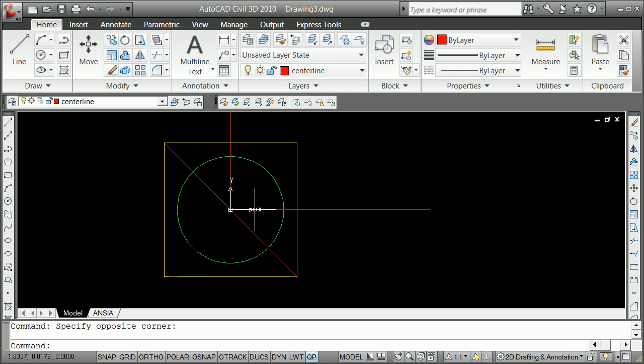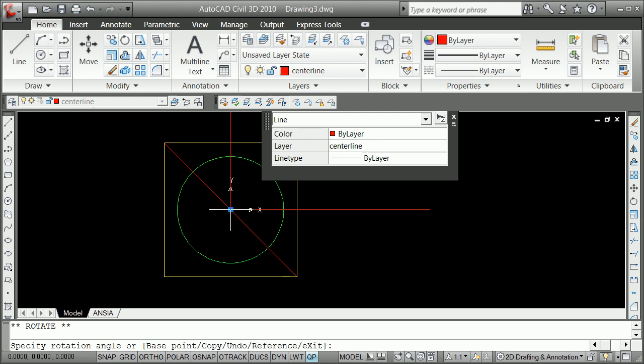Finally, we remembered in class, we're almost getting there. We wanted to make a tooth of a certain degrees. In class, you had to know that you want to pre-calculate very often, or get used to knowing that if you're going to divide a circle up, you need to know that a circle is 360 degrees or 2 pi radians. So I was going to divide mine into 60 teeth. So the way I can do is I can grab that, I can left click, spacebar, get to the rotate, say C for copy, rotate. In this case, I'm going to go in a clockwise direction, so -6 degrees.